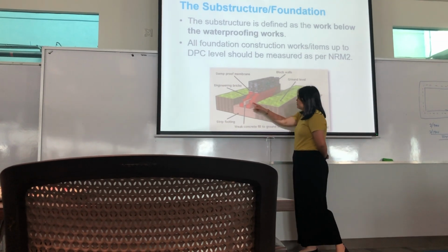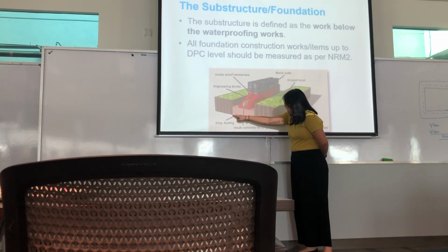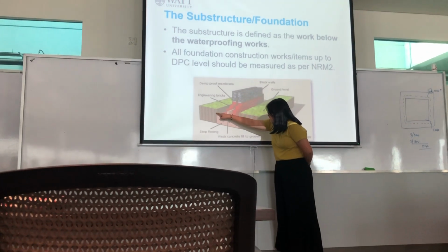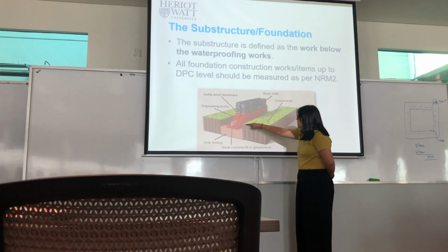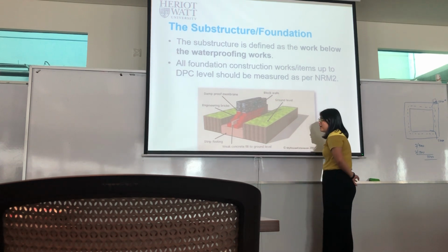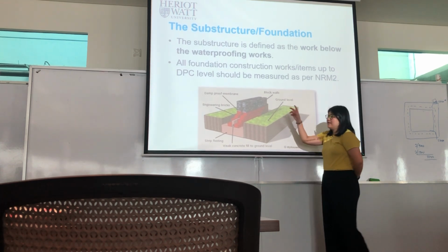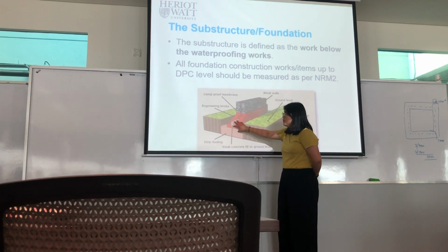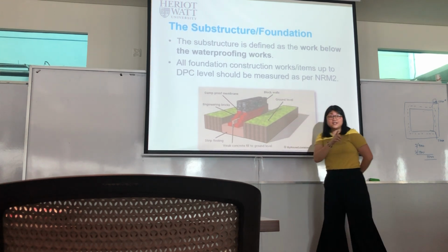So what you do, the first step, you have to do this excavation, okay? After you have done your excavation, what do you do? There are things that you cannot see from here, but you need to do. For example, you excavate, where do you put your soil? You need to measure that.